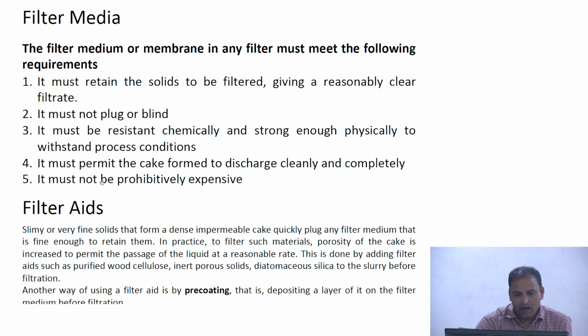The other requirement is that it should permit the cake formed to be discharged cleanly and completely. Once the filtration is done, the solids are deposited on the filter medium, so there should be some easy way of discharging the solids. And of course it should not be expensive. So those are some of the requirements of a filter medium.